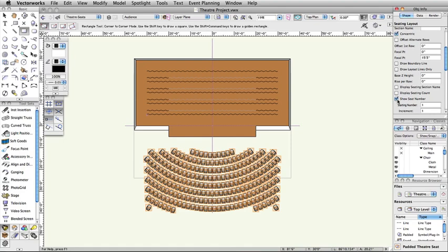We are going to use the Clip Surface command from the Modify menu to remove a center strip of the seats. First, we need to create a rectangle to use as the clipping object. Activate the Rectangle tool in the Basic palette. Switch to the Midpoint to Corner mode, which is the third mode.